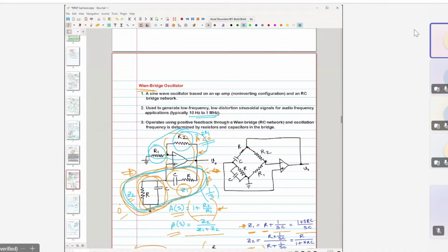Okay, so far we have seen the oscillators which can produce a sinusoidal waveform. Now let us deviate a little bit from that and see whether we can generate a square wave using an op-amp circuit. The answer is yes. We can use a Schmitt trigger based oscillator to generate this type of waveform. To understand this, let us first briefly discuss the op-amp comparator.